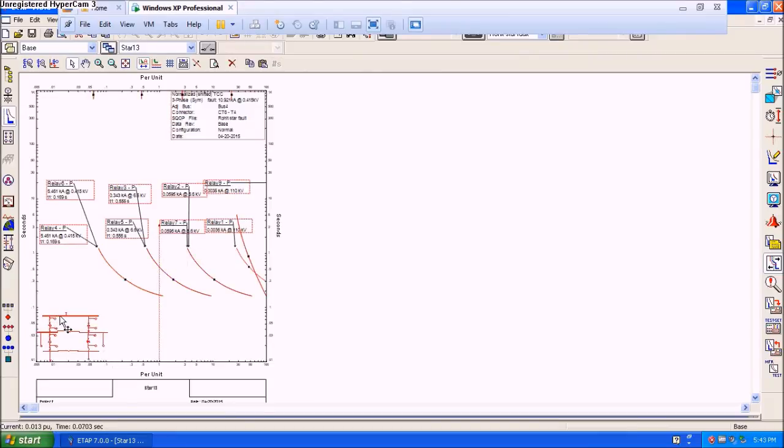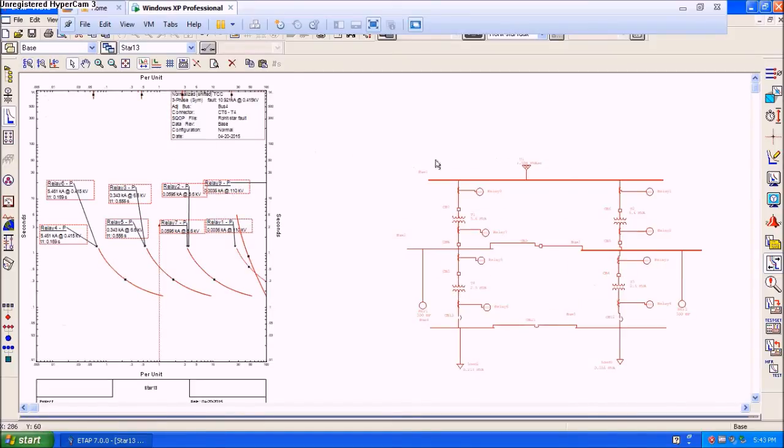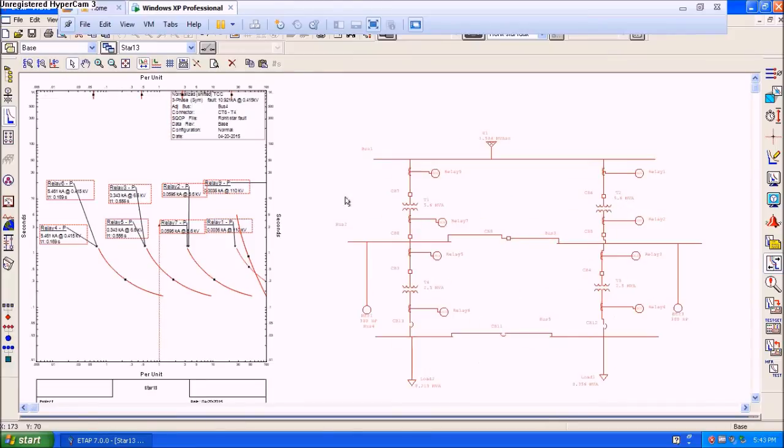The main problem will come when a fault is created in between relay number 6 and 5. Then we have to give a setting which is the pickup range of the currents. Suppose a fault is nearer to relay 6, then the fault current will be more. According to that, we will give a time setting which will be less, so it will operate first. Then the current will go slowly upside, and the intensity of the current will automatically decrease. So relay 5 will get more time, we will set the time setting accordingly, and relay 5 will operate after relay 6. This is the main concept.